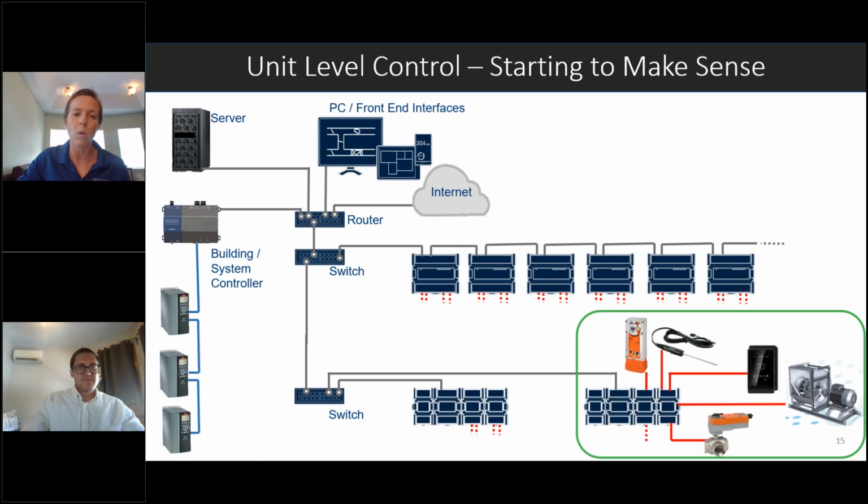And that's typically how your building automation system would connect to the owner's LAN, whereas this building controller would have an IP address, and it's kind of how everything would get connected in the tiered architecture. But in this diagram where we have all BACnet IP controllers, just because there's so much horsepower and processing speed, much of the intelligence is distributed and decentralized, you no longer necessarily need to have that higher level building controller.